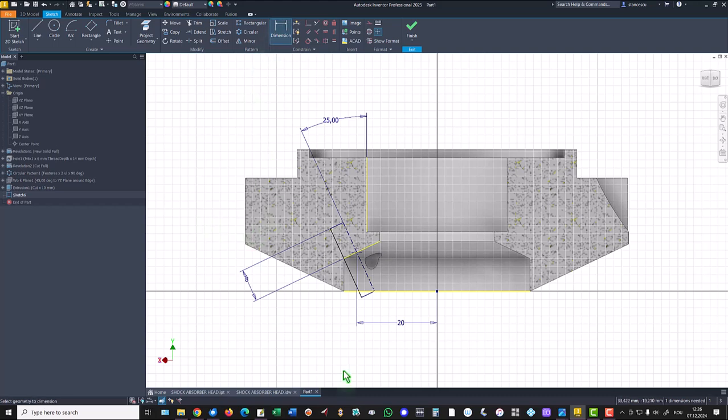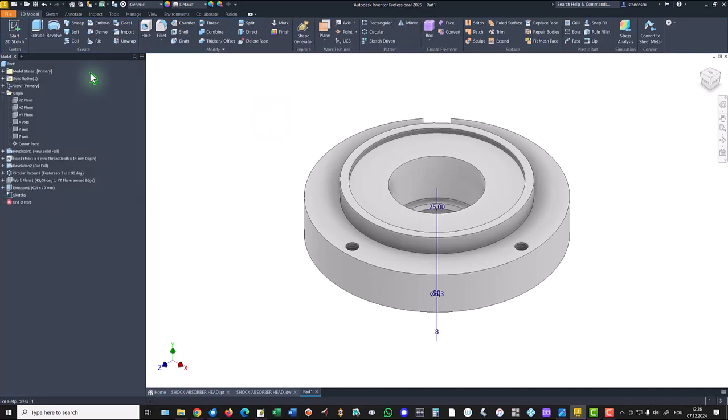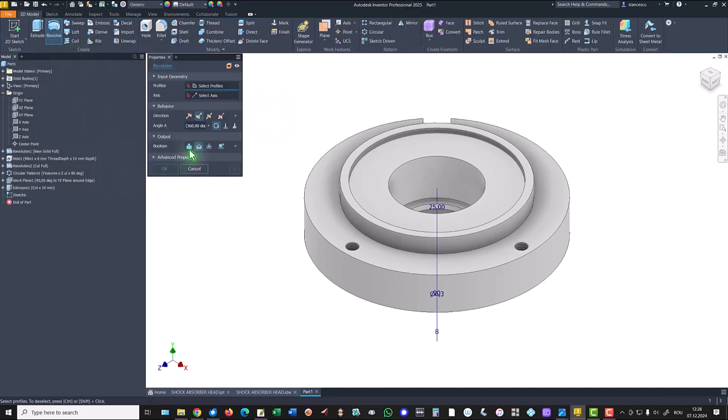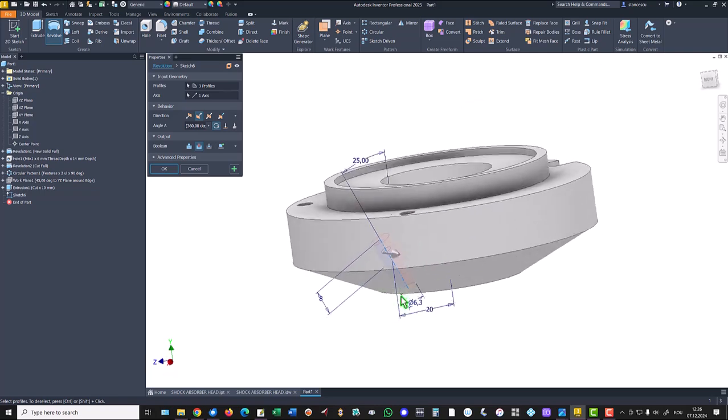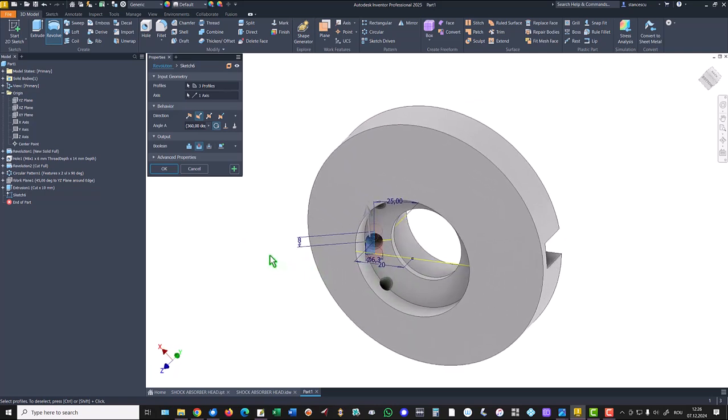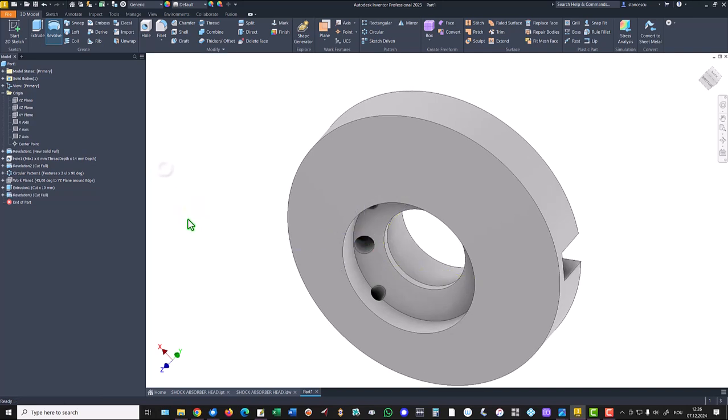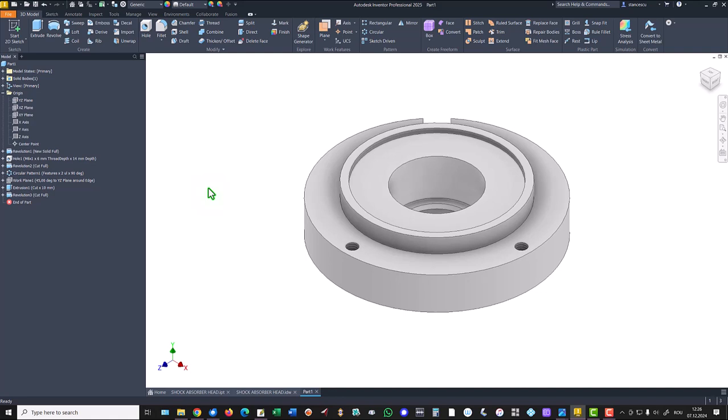The diameter is 6.3. Okay. Finish sketch, revolve, with cut, select profile, select axis. I select the profile, this is the profile, and when I go here, Inventor knows what is that axis. With cut, okay. Good.